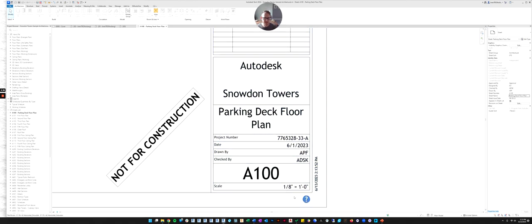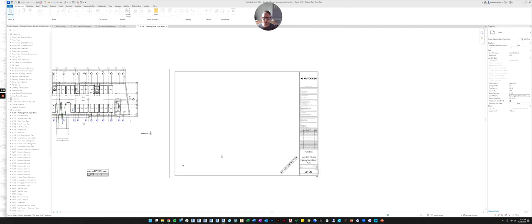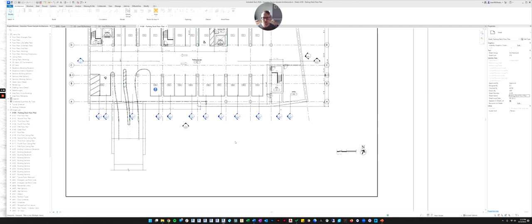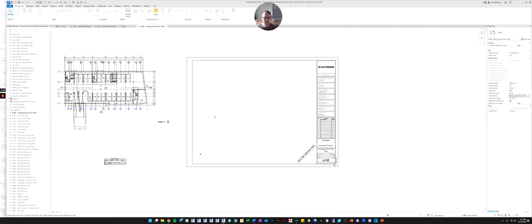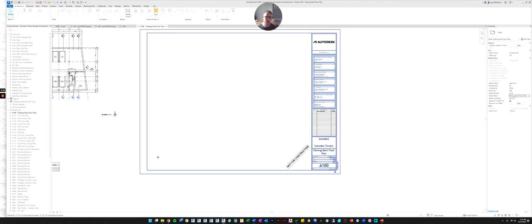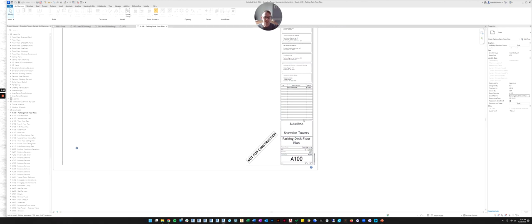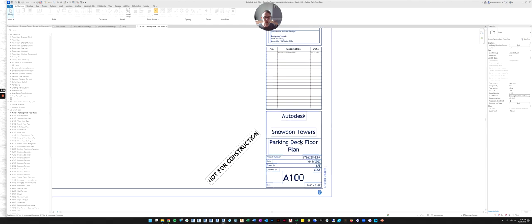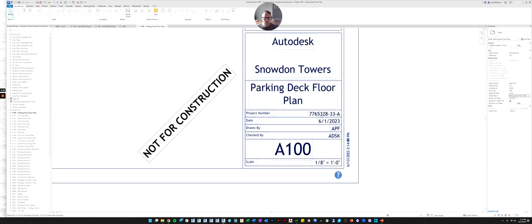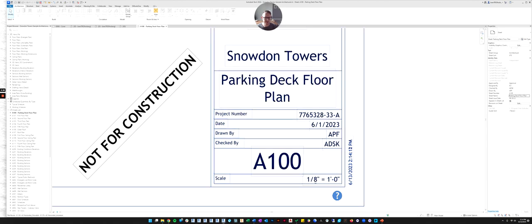It often has the scale at which the sheet is drawn, or sometimes the scale is displayed with the name of the view. You can find it in either place or one or the other. It usually has logos for the people designing it, and customer information and the project name. So let's start at the bottom here. You see the scale, you see the sheet number.